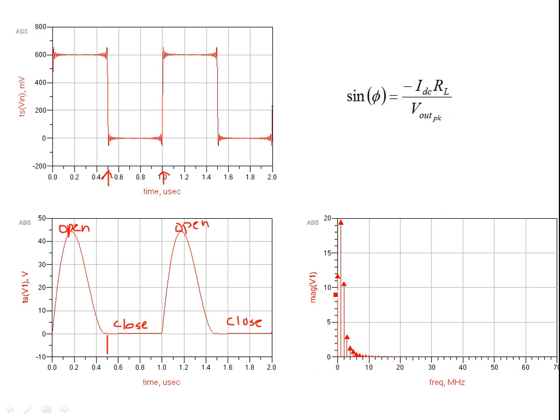So the harmonic content is as such. We have DC, and we have the other harmonics. For example, the second harmonic is considerable as compared to the first harmonic and third harmonic. So the harmonic content is significant. It's not a very nice sinusoidal wave, where the fundamental is more pronounced. We don't have anything like that over here.